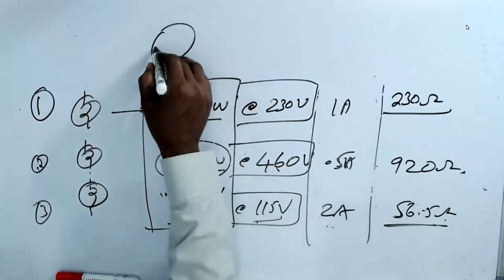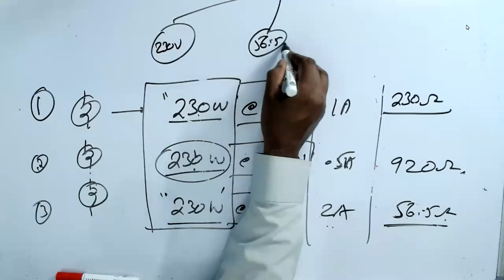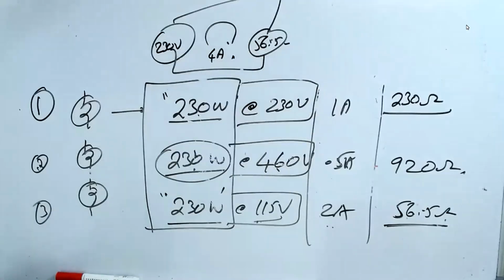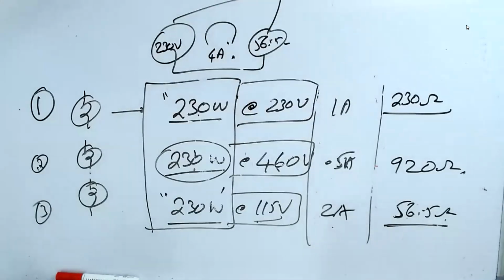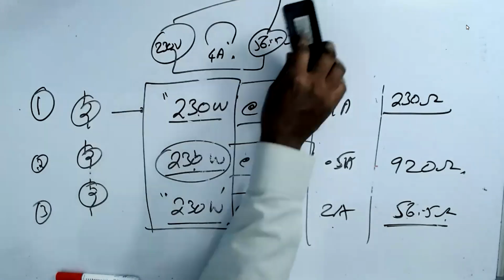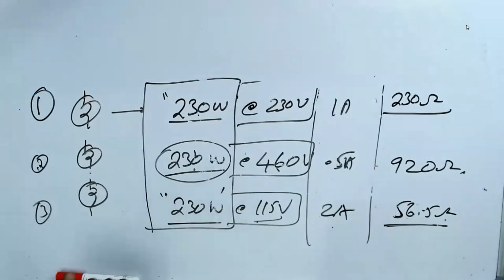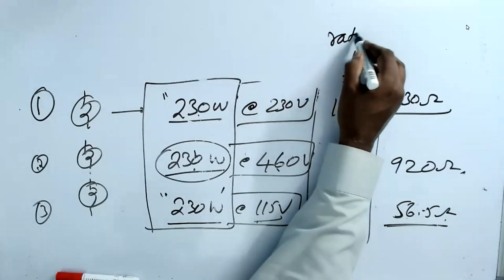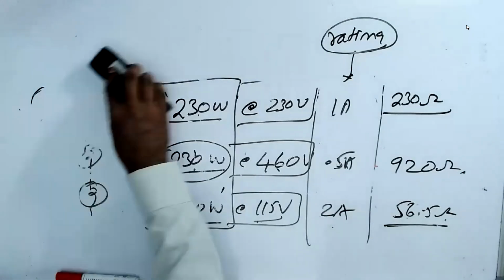In India, you give a 230 volt supply to the 56.5 ohm. The current is going to be huge, 4 amperes. And this guy can withstand only 2 ampere. So this guy blow up. The bulb is gone. Understand now? That's the way the whole technology works. This is called rating. So every device, today, that is the trick here. This is very important for us.